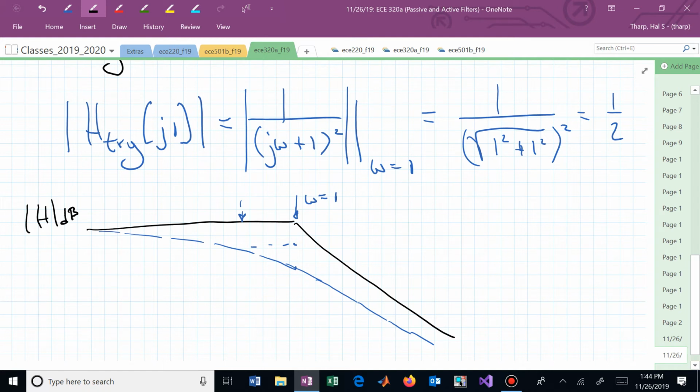So we are going to pick up next time in a week figuring out how do we design Butterworth filters, because we want to overcome this dilemma. We want to make sure that if we increase the filter order to 2 to 3 to 4, we still keep our cutoff frequency at 1. And that's going to mean that we can't just keep adding poles at -1. We have to create our pole pattern in a Butterworth pole pattern. And we're going to learn how to create Butterworth pole patterns in a week. And if you're anxious, you can read about that over break.